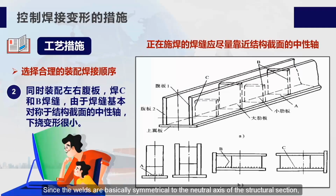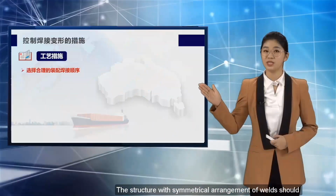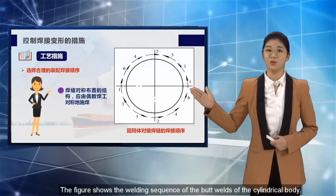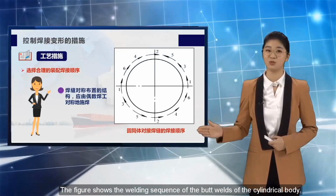Since the welds are basically symmetrical to the neutral axis of the structural section, the downward deflection deformation is small. The structure with symmetrical arrangement of welds should be welded symmetrically by an even number of welders. The figure shows the welding sequence of the butt welds of the cylindrical body.